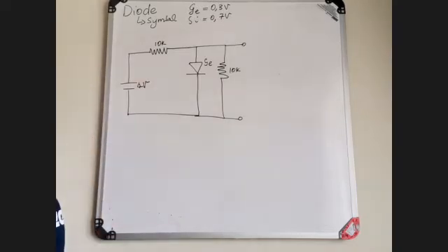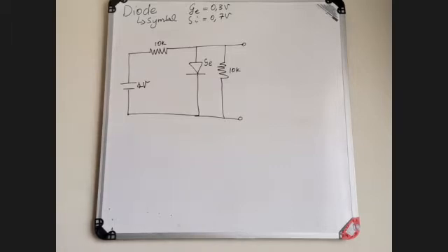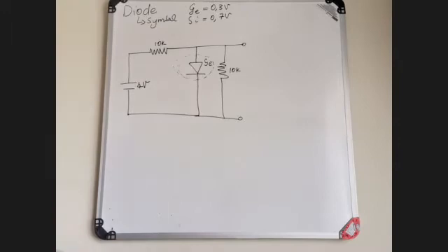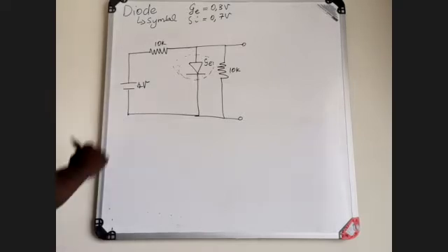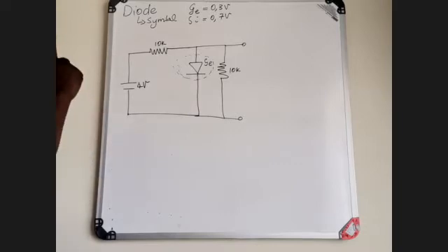We know that when it comes to an electrical circuit, you have a series connection and a parallel connection. The series connection comes with its own characteristics, and the parallel connection comes with its own characteristics. If I look at this connection as a parallel connection, I must recall the characteristics of a parallel connection. On a parallel connection, the current must split, but the voltage remains the same. Now, if the voltage remains the same, because this component is a semiconductor component, then we'll check how this voltage of 4 volts compares to the voltage drop that can exist within this component during bias.